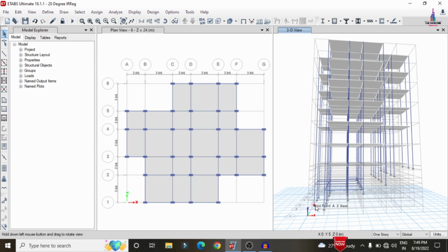If you want to calculate this dimension, you need to know the height. Here I am taking 3 meter height and a length of 3 meters. If you apply tan 20 degrees, it will give you the height for this slope. In the same process you can calculate the height for each respective slope.